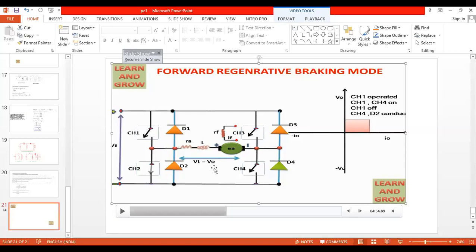So when electric train is approaching a nearby station, electric braking is used to stop the electric train. During this process, the motor inside the electric train will act as the generator, and the motor back EMF voltage will be greater than the inductor voltage and the supply voltage. Therefore, energy starts to travel in opposite direction or reverse direction from motor. You can see here this will be plus. Therefore, now the current starts to flow from the motor which is acting as the generator. That means if I am stopping the electric train, at that time also I am generating the electricity.